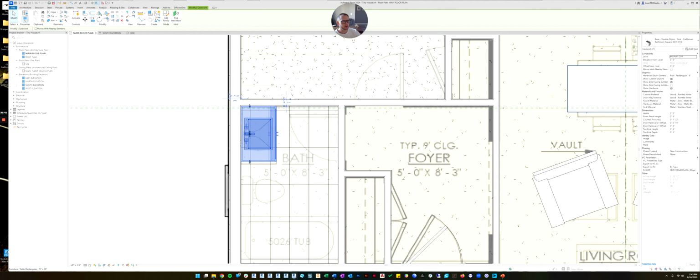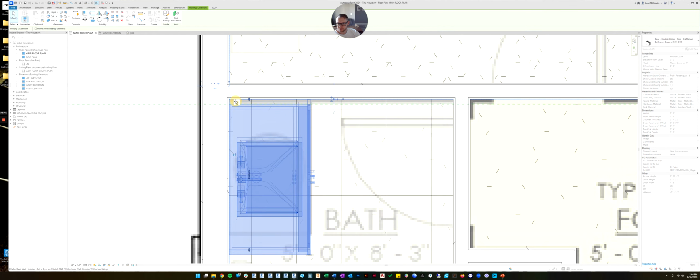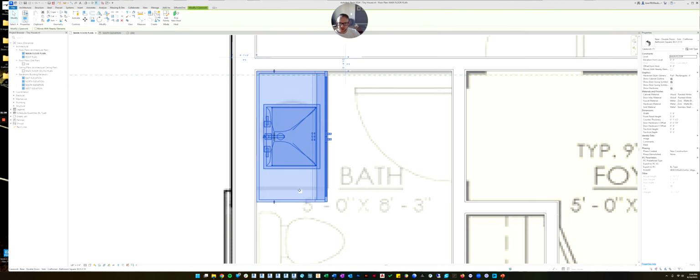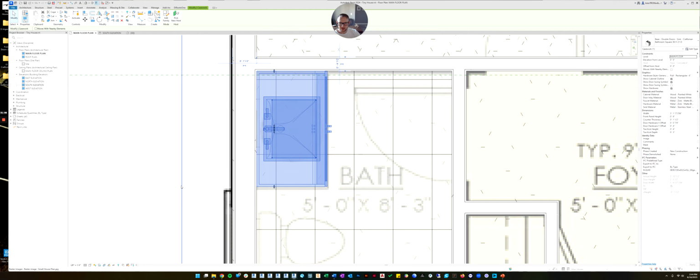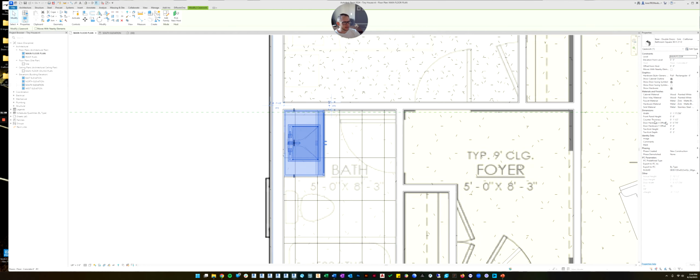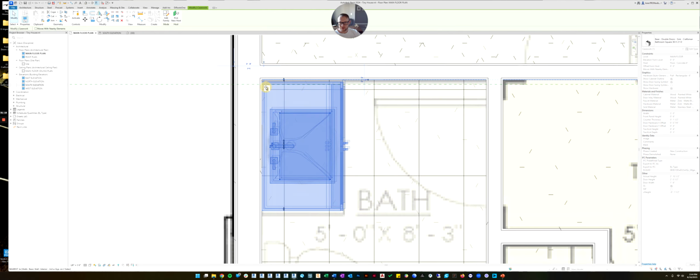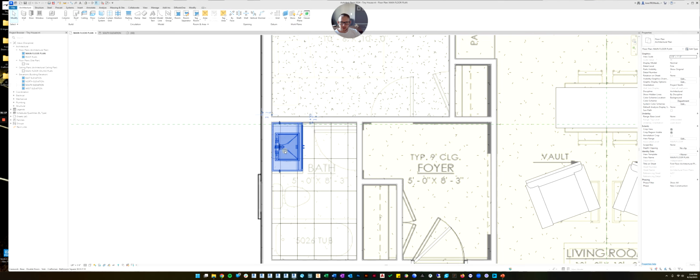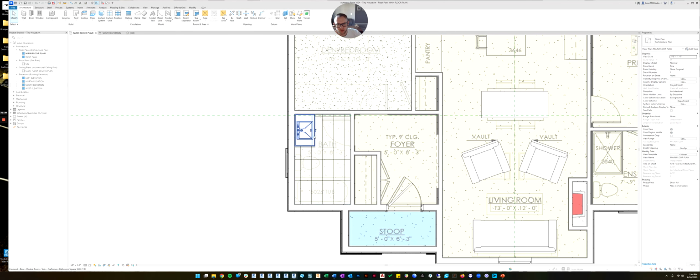You can experiment with them, but one of the settings that you're really going to care about is the width of the sink. Right now it's 3 feet, but you can change it to 3.5 if you want. But then you need to come back and recenter it and put it back on the wall here. The other thing you can do is drag it to the length that you want, but that's less precise than putting in exactly 3 feet, and then it'll make it exactly 3 feet for you. So that's how you would use that cabinet.